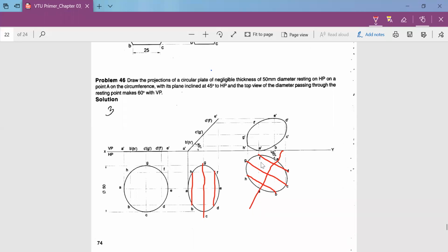After drawing the perpendicular lines, now it's very easy. You know E and A, so identify the other points. From this point to F, measure the distance using the compass. Come back to this point and cut an arc on the perpendicular line that you have drawn. Similarly, from this point to D, it will be the same as from here to F. So measure this distance, come back to this position, and cut an arc on the perpendicular line that you have drawn. So name it as